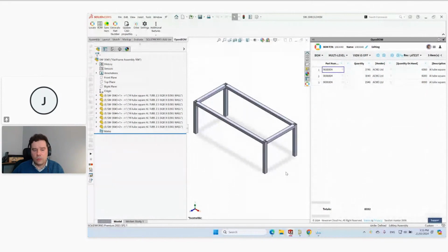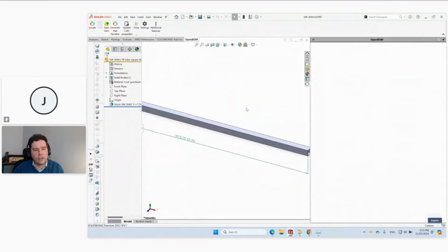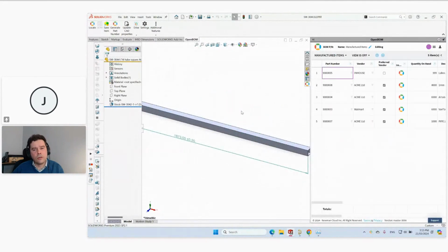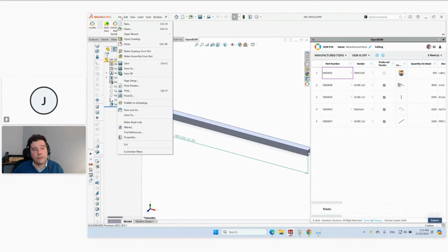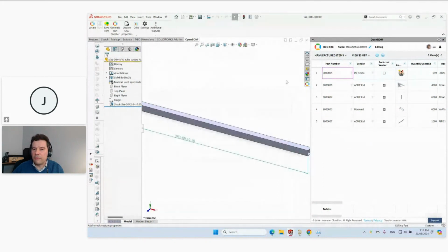For example, for SolidWorks, it's actually possible to change the quantity that you use, to a different field instead of each. So if you look into SolidWorks and go into the property of a component, you can actually say the BOM quantity is not each, it's not how many you have in the assembly. It can actually be driven by a property, for example, length. And OpenBOM integrates with this. So we have the best integration in the market.